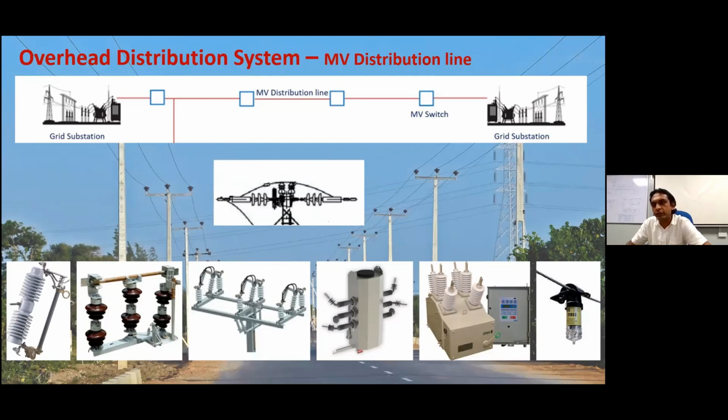In addition to that, I saw another picture. This is called a fault indicator. It is very useful, as Prabath mentioned during his presentation. He said if you can identify a fault immediately and remotely, then we can switch the switches on and off if you have an automated system. So this is very useful for identifying the fault. Therefore, it's called a fault indicator. This is also integrated with the remote terminal unit, and it communicates with SCADA or other systems. We will discuss more in future.